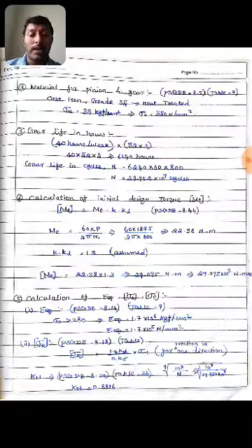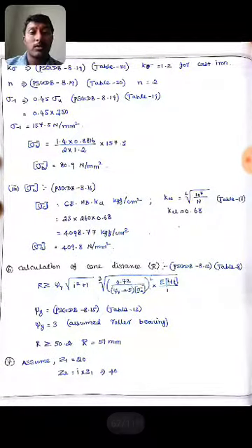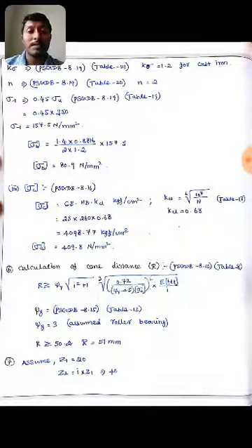Next, design sigma B from the PSG data book page number 8.18 table. Design sigma B is equal to 1.4 KBL divided by n into K sigma into sigma minus 1 for rotation in one direction. KBL from the PSG data book page number 8.20 from the table 22. KBL value is taken 0.8816.